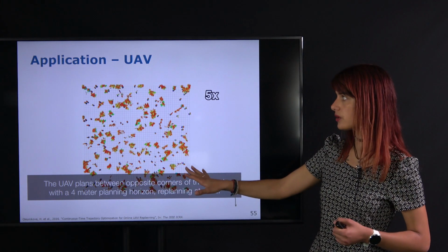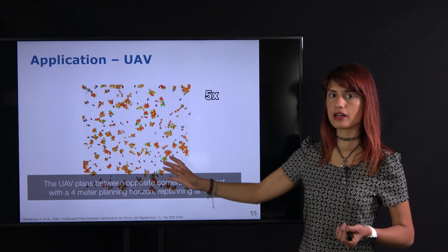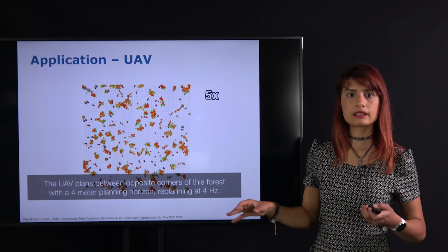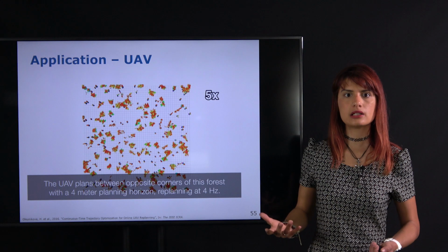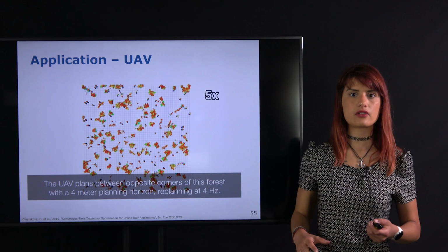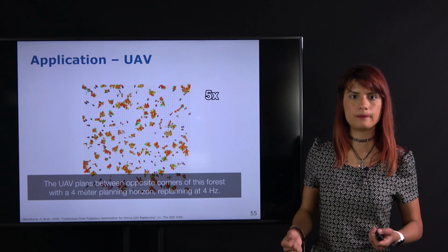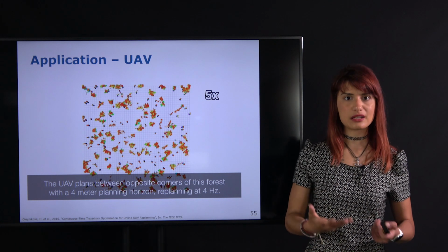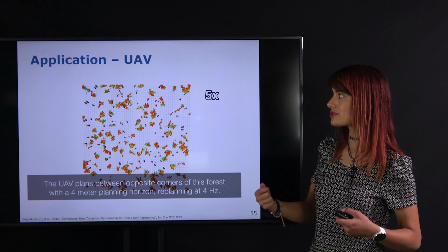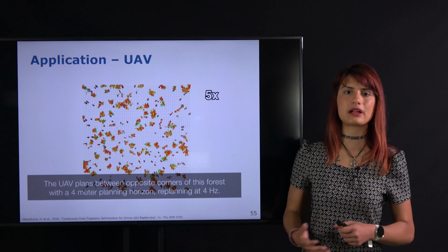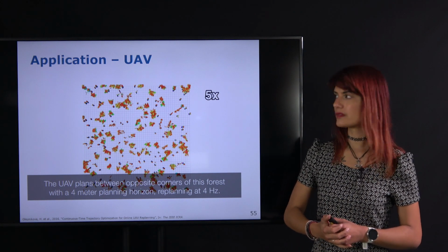We will see a UAV trying to plan a path from the top left to the bottom right. In this case, our global plan would simply be a straight-line connection, assuming that the environment is initially unknown. This is not very complicated, such as the A-star or the RRT, but it's just to illustrate the differences between a global and a local plan in this scenario.